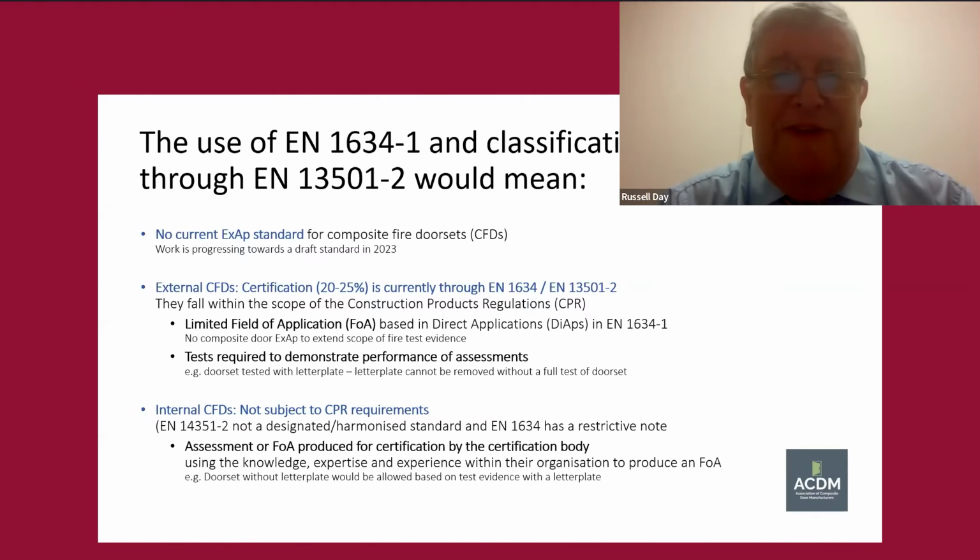If they don't have that assessment produced, the results are only applicable to a door, for example, of exactly the same specification and size as that one tested. So to meet the market, we would end up testing thousands of doors simply to get the scope that we needed. Following Grenfell, the term assessment, and particularly global assessments that we used to use, became quite a toxic term. And therefore, we tend not to use that anymore. We talk about a field of application, which is a term used within the 13501 Part 2.